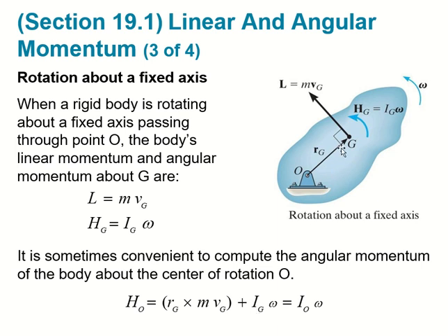First, we get the momentum at point G, which is this. Then we account for the regular linear momentum part, which is m v_G, and that is about r distance away. So this point O and G are r distance away from each other. See that?